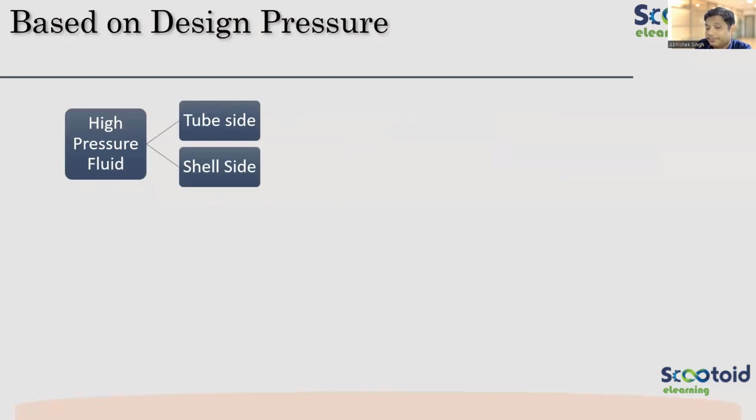Now tell me, if I have a very high temperature on one side and a very low temperature on the second side, the temperature difference is very high between the two fluids, then what will you be using: fixed, U-tube, or floating type of heat exchanger? Rajkumar is saying floating, Vabo is saying U, Shriram is saying floating. Glad to see that nobody is saying fixed.